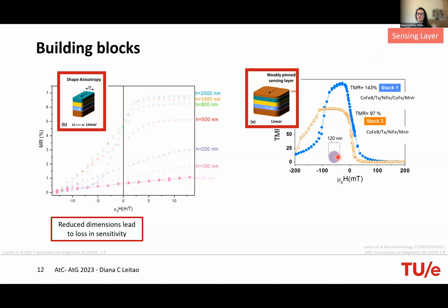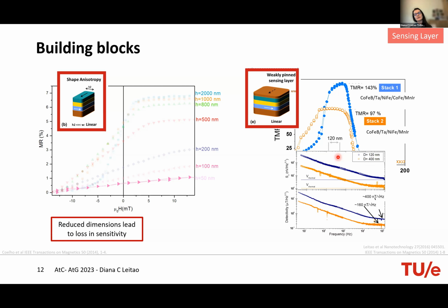Because if you want to have a very highly resolved mapping of the field, for these particular magnetoresistive sensors, it does change, or it does depend on their size. So we need to ensure that even for these small sizes, we have a linear behavior. But as always, being able to linearize, even at such a small scale, comes at a cost. And one of the key points is that using this strategy, which may seem quite nice and flexible at first, we have quite an increase in the noise level at the sensing layer.